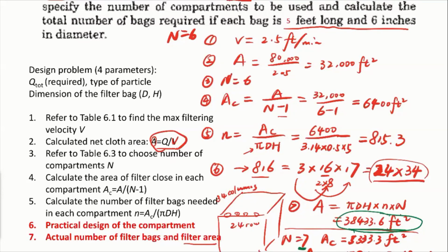We introduced the gravity settler, or the settling chamber, which removes particles by gravity settling. We talked about the cyclones, the ESP, and now the baghouse filters. For each of the PM removal devices, you need to know the mechanism and also the design criteria for these systems. We can probably go through everything during our review session next week. But for this week, the homework is still mainly focused on the design of the baghouse filters, so you can get more practice on that.